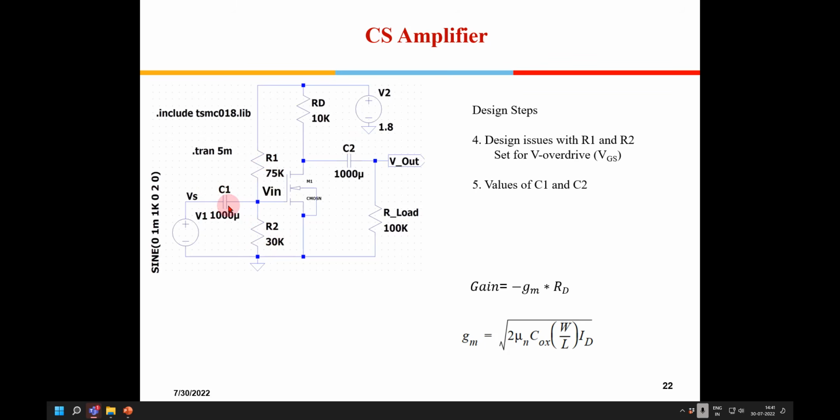That will be a high pass filter, and if I am talking about 1 kilohertz, the cutoff frequency of this filter should be 1 kilohertz divided by 10, that is 100 hertz, so that this 1 kilohertz can smoothly follow. That is the design criteria which I am going to use. Is this aspect clear to you? What I am talking about?